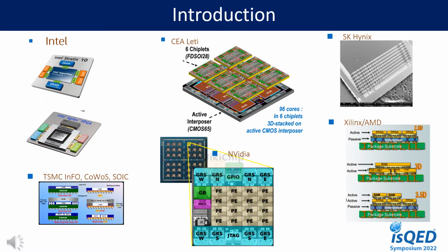However, between 2.5D with an interposer and active chiplets on top, or 3D with active interposers and active chiplets on top, or a combination-based approach, there is a trade-off between desired performance and the overall assembly cost. For example, Intel adopted the 2.5D EMIB approach with Stratix 10, 3D Foveros technology with Lakefield, and even a combination of 2.5D and 3D stacked chiplets with the Xeon graphics family.